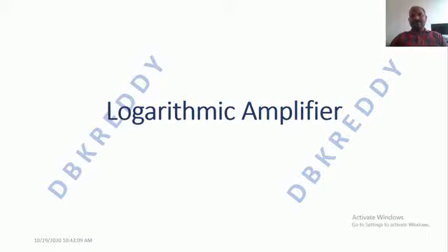For example, till now we have seen different types of amplifiers like the instrumentation amplifier and other amplifiers that you would have used in the amplification process, as well as in our filters. We have used the operational amplifier, but those amplifiers' outputs are represented either in terms of current or voltage. Till now we have not seen the output of an amplifier in terms of the log. So in order to show the output in log format, we are using the logarithmic amplifier. The logarithmic amplifiers are amplifiers only, but they represent the output in terms of the log.